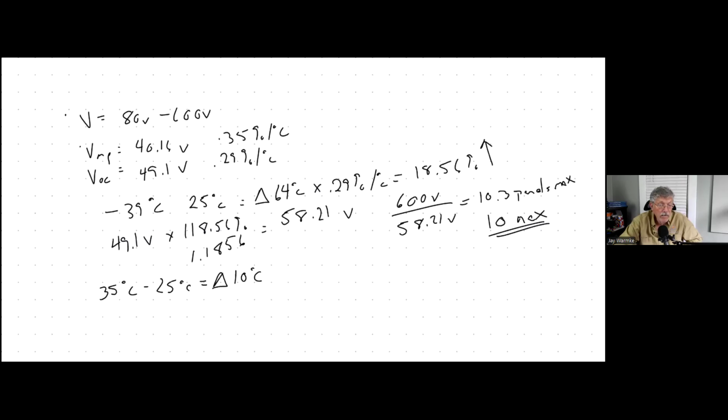But because it's hotter on a roof than ambient air temperature, the heating and air conditioning guys have said for rooftop, we add 35 degrees Celsius. For ballasted systems, we add 30. And for ground mounted systems, we add 25. So we're going to add 35 degrees Celsius. And now we've got a delta of 45 degrees Celsius.